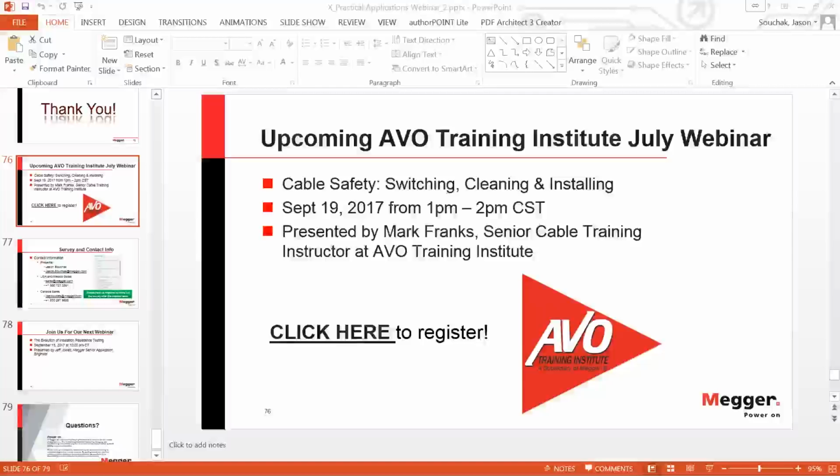Well, in my opinion, if you want to fingerprint a new cable, tan delta will not be a good tool to do that. I think Jason alluded to it, because tan delta is a measure for the aging condition of the cable. Now, a brand new cable shouldn't have any aging condition in it, so you're not going to get any result. You might even get a wrong result, because a brand new extruded cable has some byproducts from the manufacturing process, and they can affect the dielectric properties in a way that it shows you maybe a higher tan delta than you really have.